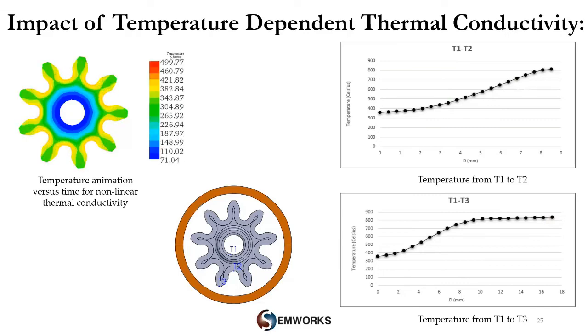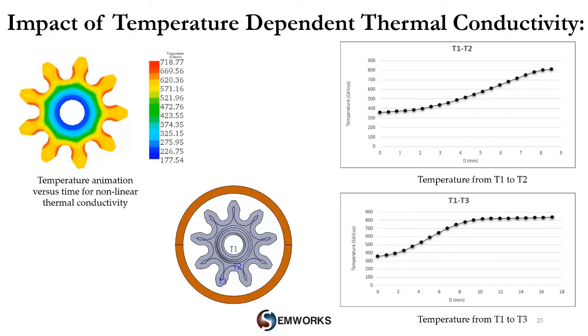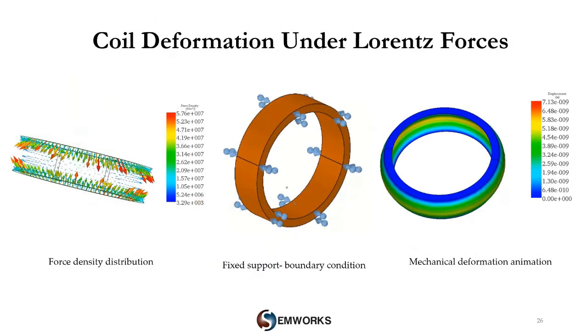Now what about the generated electromagnetic and thermal stresses? High current may result in higher thermal stresses and Lorentz forces in both gear and inductor parts, which lead to structural deformation. EMS can be used to analyze this behavior. In addition to temperature, EMS computes Lorentz force in conductors with currents, and both of them, I mean the thermal response and the electromagnetic, including the Lorentz and magnetic forces.